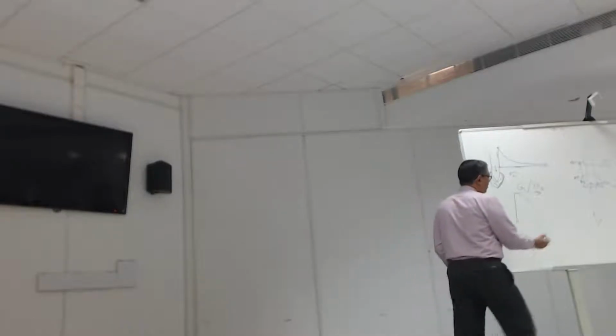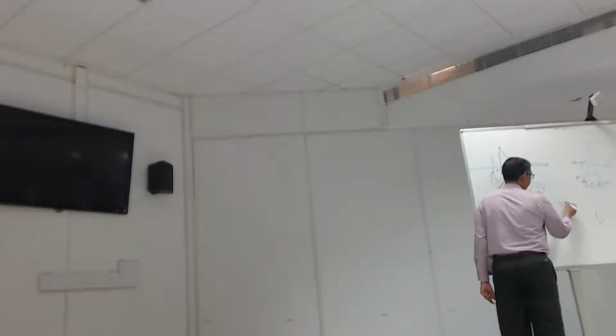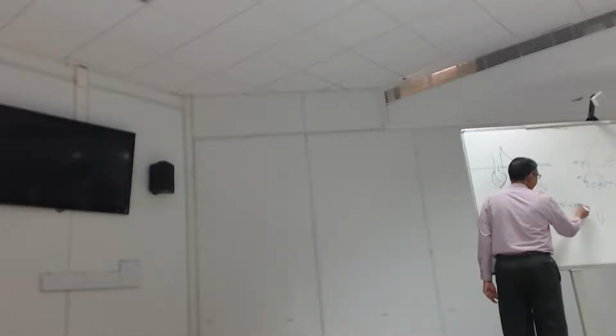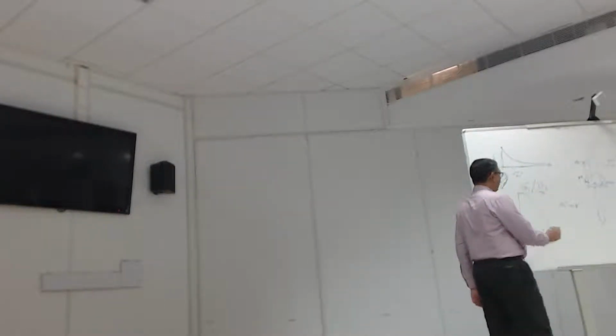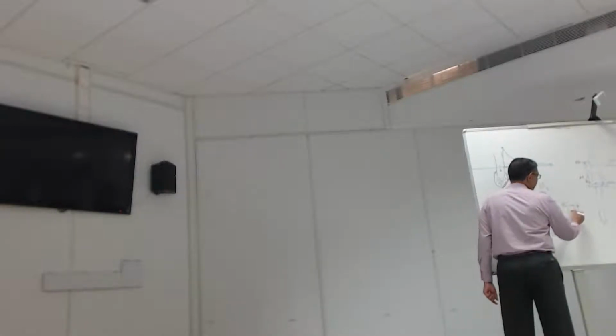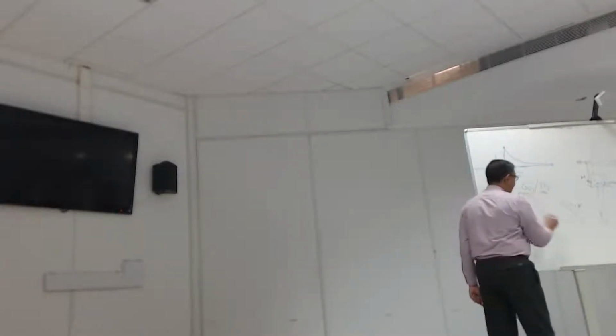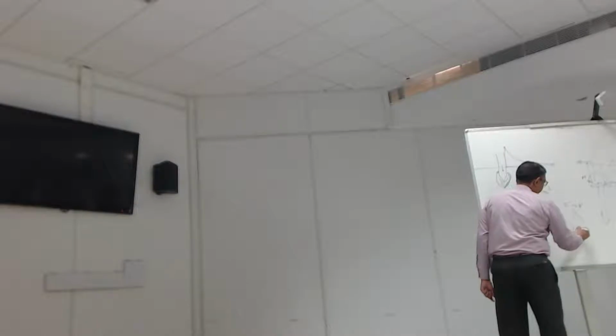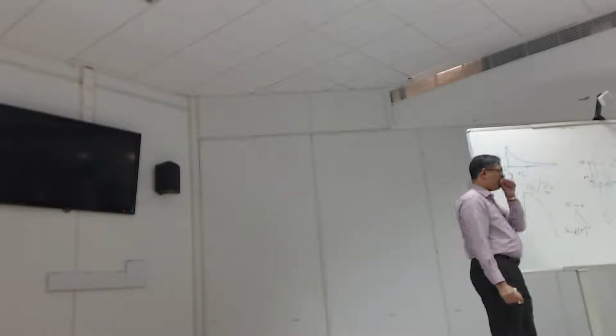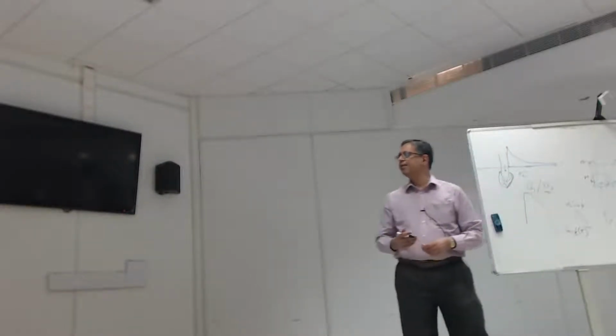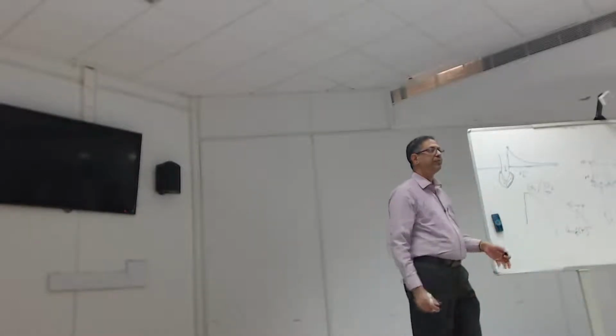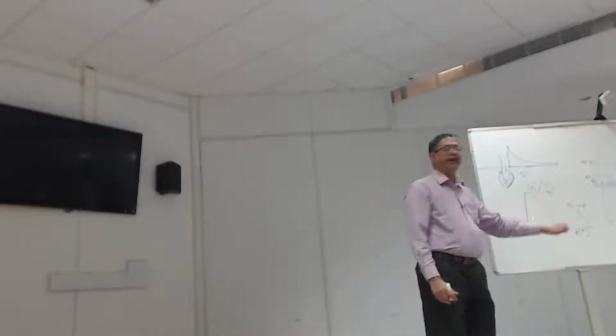So we know my vertical stress and therefore my mean confining pressure increase linearly with depth. And G is roughly a function of p' to the power of half, so it should be some kind of a parabola. Okay, so that does not need much explanation.